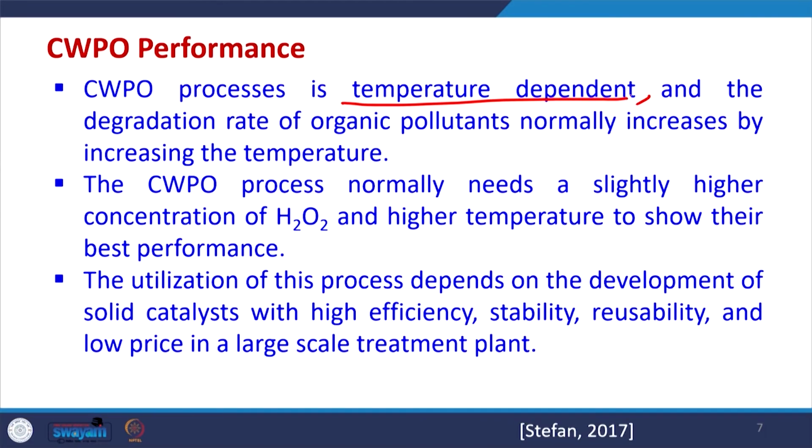Now, how does CWPO performance work? It is temperature dependent, and the degradation rate of organic pollutants generally increases with increasing temperature. The CWPO process normally needs a slightly higher concentration of H2O2 and a slightly higher temperature than ambient to show its best performance. What we do is try to find out the amount of H2O2 required, with respect to the stoichiometric H2O2 requirement.